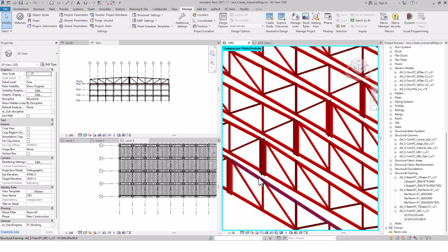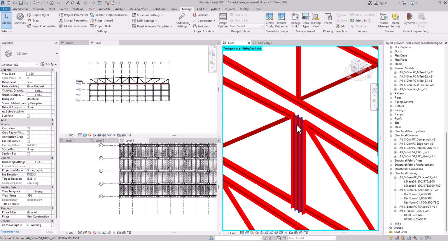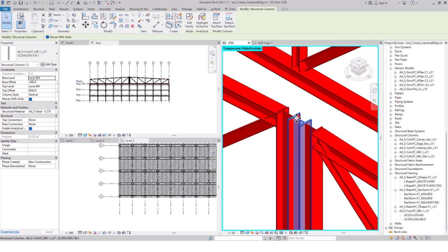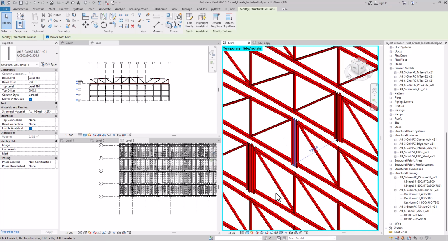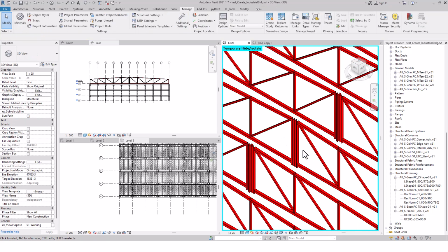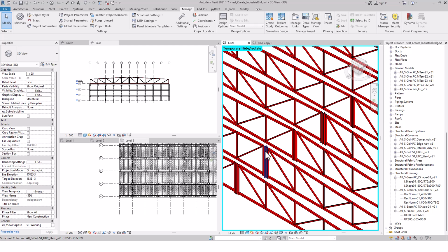The main intention is that there is a precast column support here, and we have 4 trusses, like these 2 trusses sitting onto the main column, and in between we have a big bracing, and this bracing will be carrying this truss as well. So this member is actually part of that bracing. This is the intention, that's why we make it that way. So now we are going to create the brace over here.